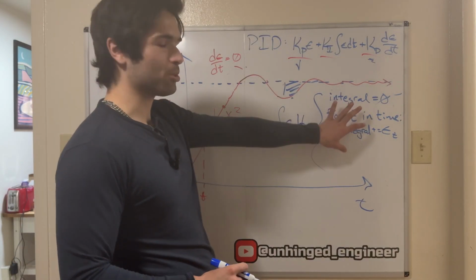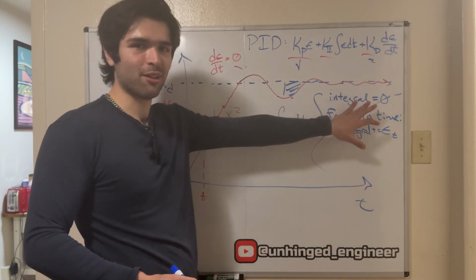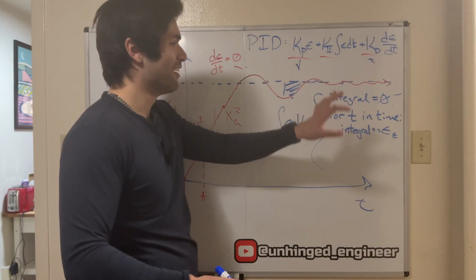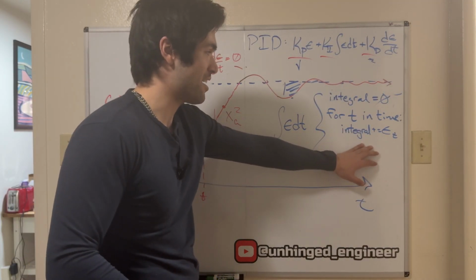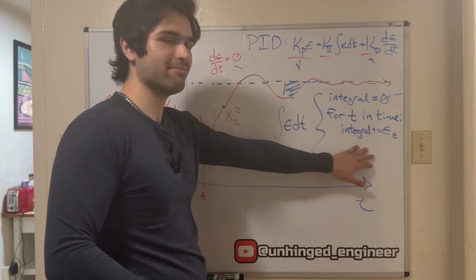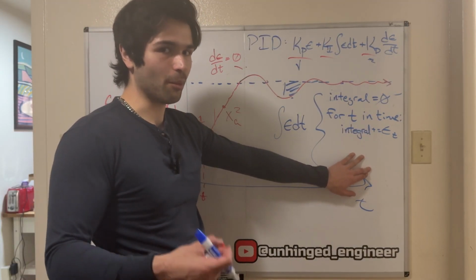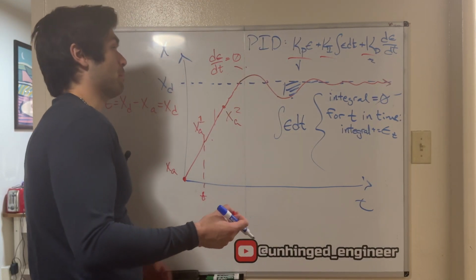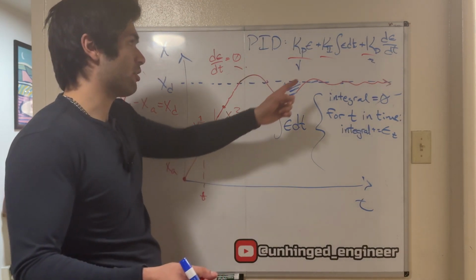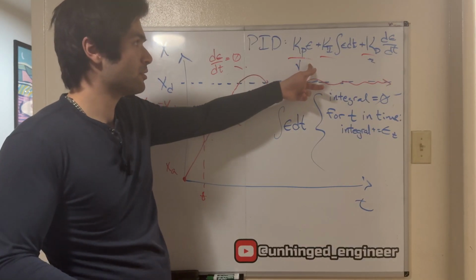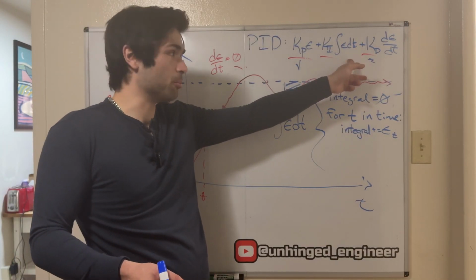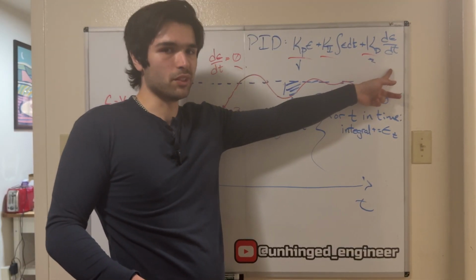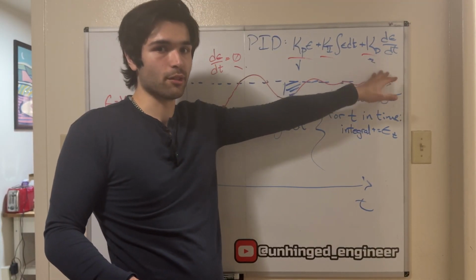And if you're a hardcore computer scientist, you're screaming at this right now, because I know there's precision issues if the number gets too big, right? But all of this is to say, you're just having an accumulator, summing it over each time step, right? So at that point, it gets really straightforward. You measure the error with your sensors or whatever else you use. You add that error to your accumulator, that's your integral, and then you subtract it from your previous time step, and you're good to go for your derivative.